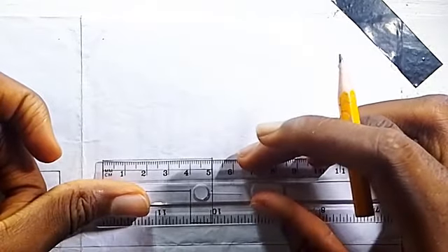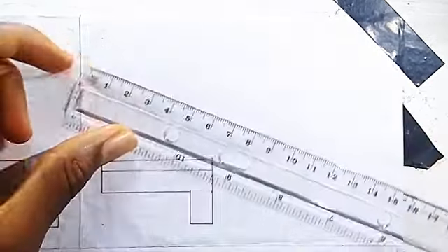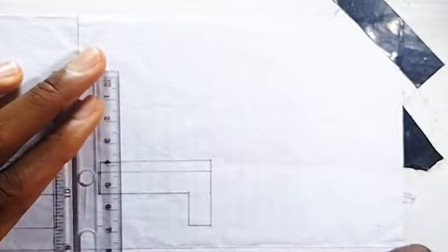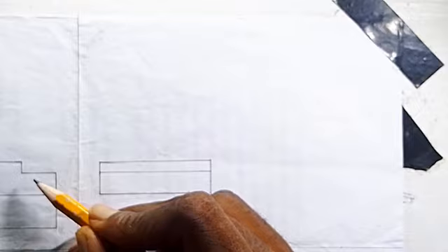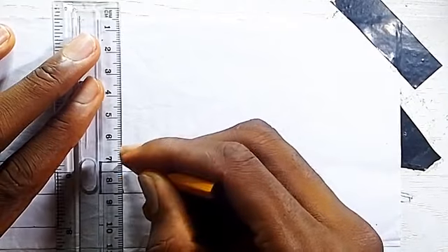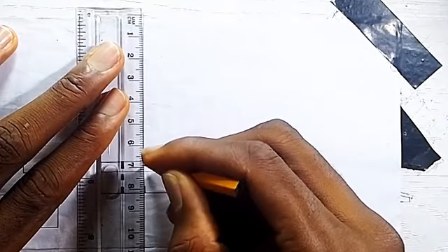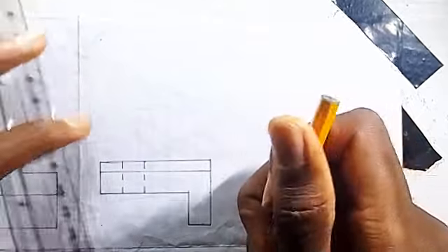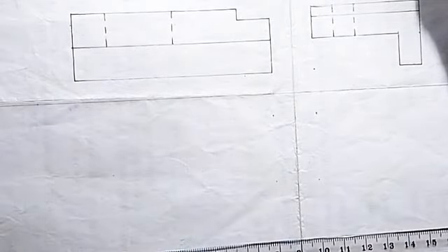Mark same thing upwards. Then draw the line of the hidden detail. Remember, it runs to this top block. So that's what we do at here, only the top layer of the block. Good, so we are done with the end elevation. After the end, what's next? The top plan elevation.